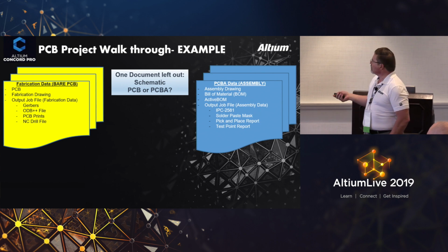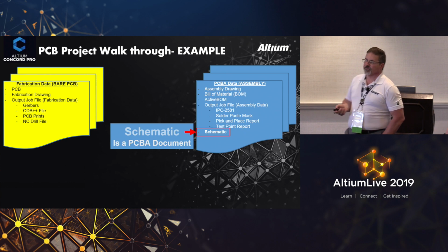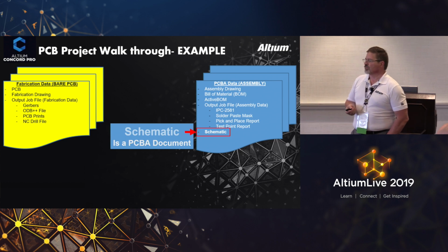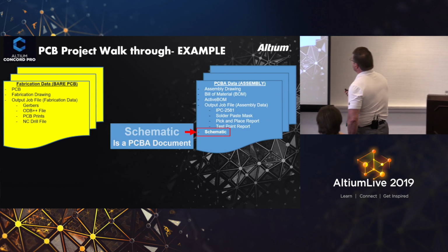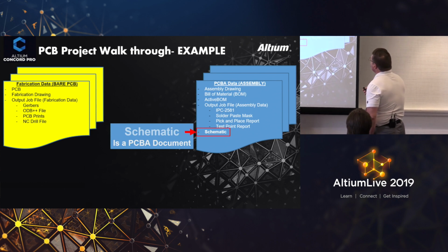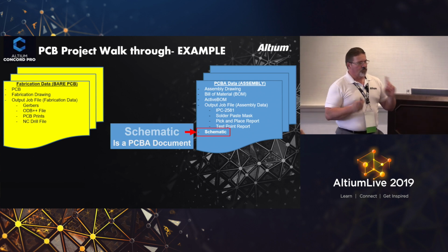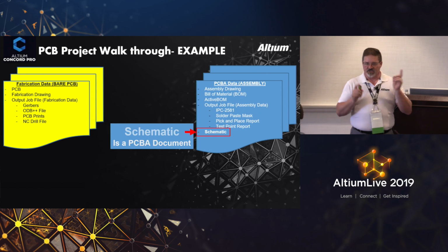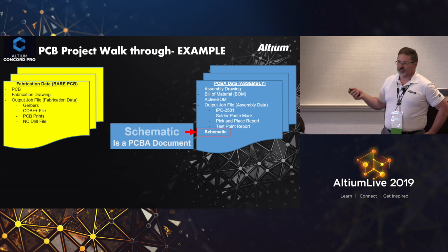All right. So what we did was we actually went ahead and put the schematic in the data package, the data side, the PCBA side. So that's where we put that. Because the one thing we wanted to make sure we kept tied together was the BOM and the schematic, so that any changes on either one of those documents, which should be from the schematic and not just the BOM, right, parent-child, they would stay synced up.